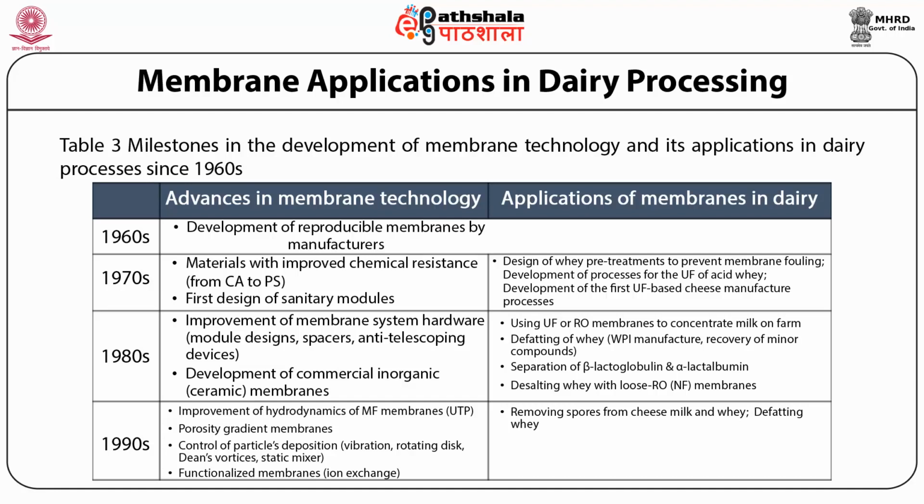Defatting of whey can likewise be done with the help of microfiltration. Separating casein micelles from milk is also done by the microfiltration process. This microfiltration process is able to remove microorganisms, fat as well as caseins, when the membrane pore size is different.